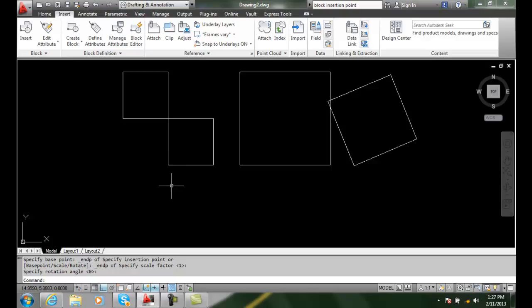So it's basically a good idea to draw things as a 2D unit block of a scale of 1 to 1. Then we can multiply things on our X and Y scales. And so therefore we can make a window 1 inch by 1 inch, and then if we want a 6-inch wall, we can say it's 6 in the Y, or 4 in the Y if it's a 4-inch wall. If we want a 36-inch wide window, we can say it's 36 in the X. If we want a 28-inch wide window, we can say it's 28. It gives us a lot more flexibility.